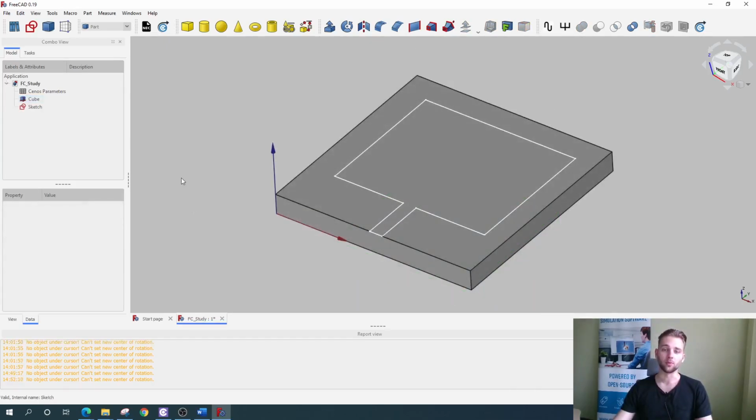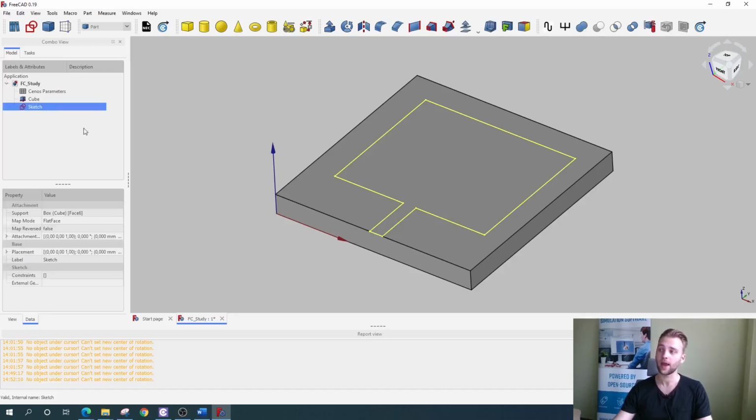You can create more complex volume shapes as well. A very nice way to do that is with extrusion function, which helps to turn your sketches into 3D geometries. For example, if you are building a patch antenna and you want to create an actual layer for your patch, then you select the sketch of your patch, like this, and click Extrude.